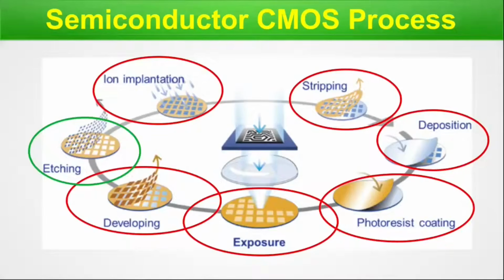It keeps on operating for formation of the metal routes in the BEOL region I have shown in the first slide. The FEOL and MEOL obviously go through this process. However, the BEOL goes through this cyclic process several times, and the step marked in green, etching, is the process step where we are using the plasma, and here are the chances of getting the antennas. Don't think that antenna violation is happening to only metal 1.